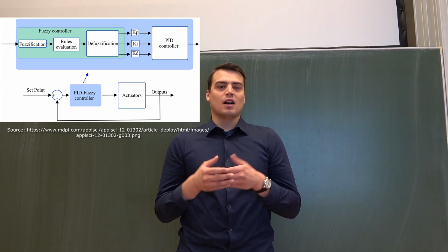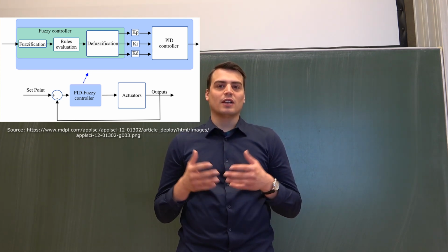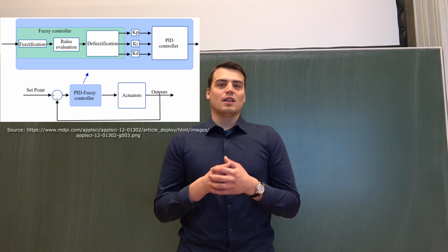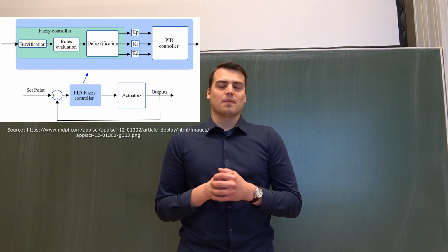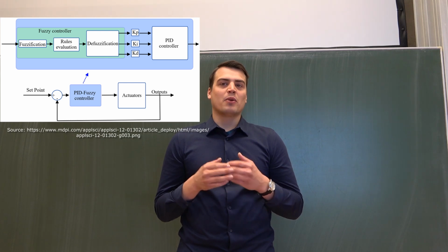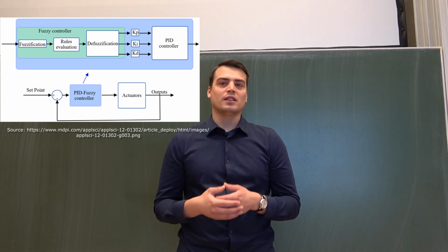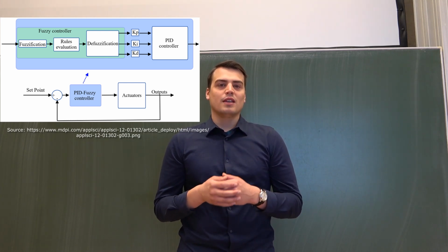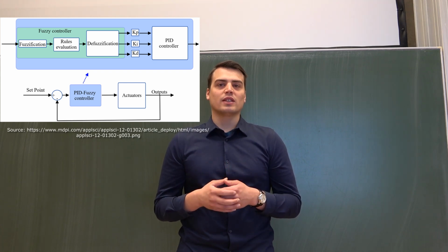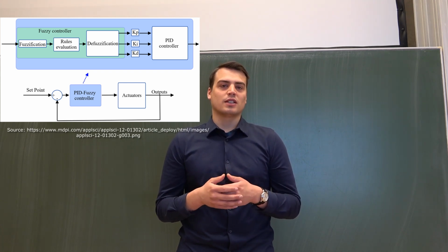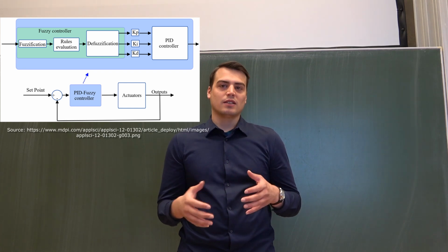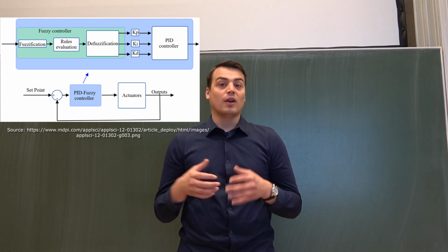But how does it actually work? What are the steps involved in this control technique? FLC operates by simulating human reasoning in decision making. It uses fuzzy logic to translate linguistic rules such as "if drone is moving too fast, reduce thrust" into actionable command.